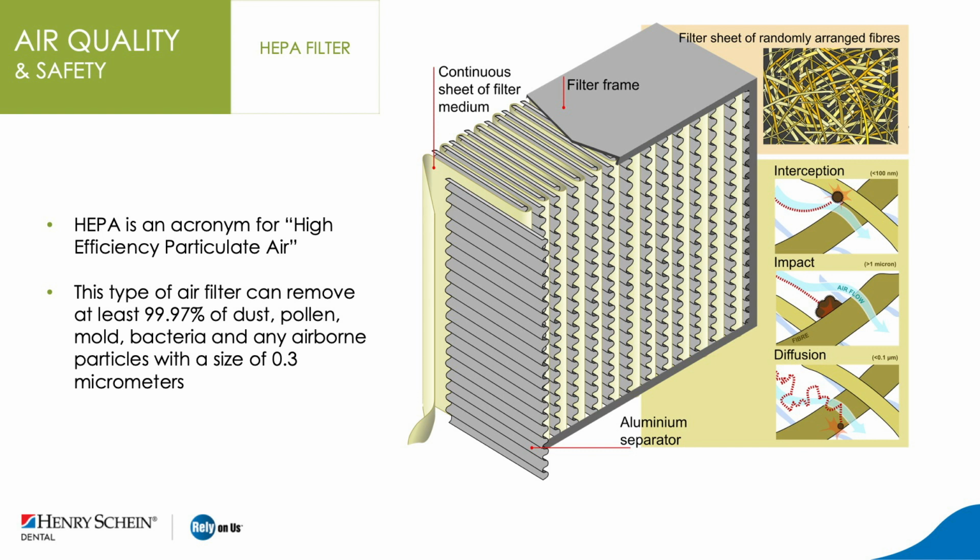Okay. Now, what about negative pressure? And what's the relative cost of that? Well, the cost of a negative pressure on a per square foot on a per ton basis is double that of a HEPA filter. So now we're up to $18,000 a ton for a negative pressure room.